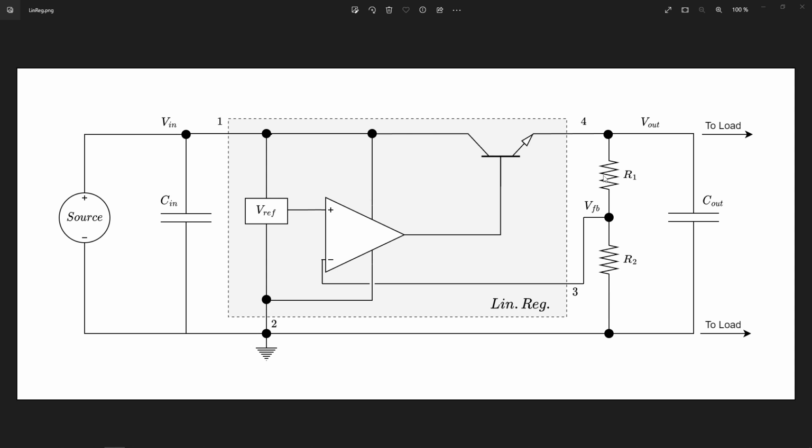we'll see later on. Our input voltage source is connected to the power in and ground terminals of our linear regulator, for which we also need an input capacitor Cin, which provides local energy storage and filtering, and this needs to be placed very close to the regulator, as we'll see in the layout and routing section. On the output side of this linear regulator, we also have an output capacitor for similar reasons, for filtering, bulk decoupling, and energy storage. From that point, after this output capacitor, we can then connect a load or loads.